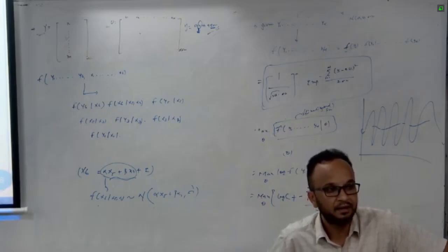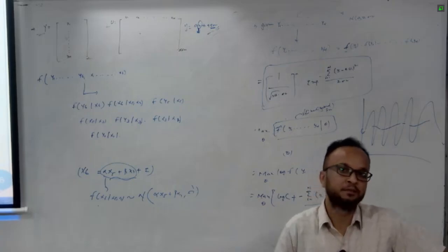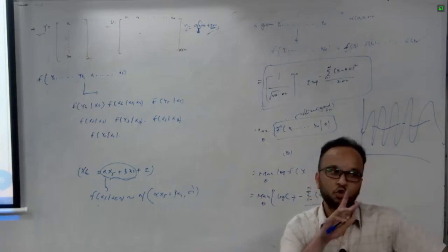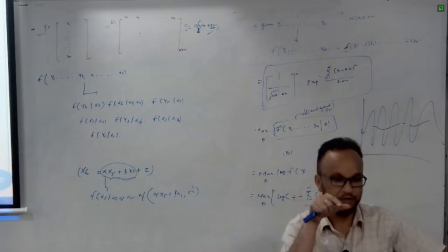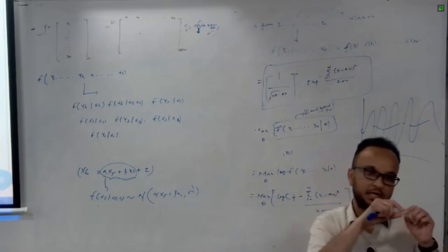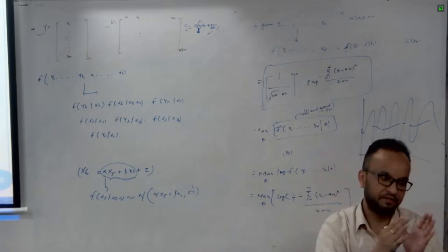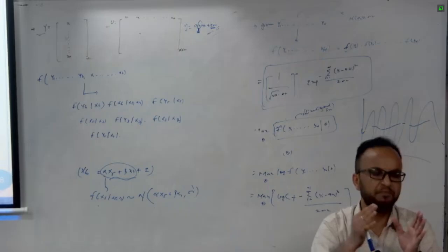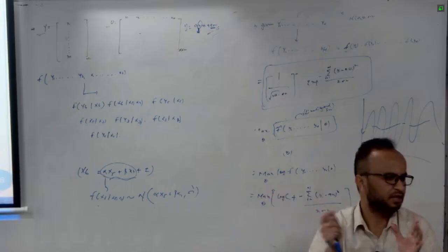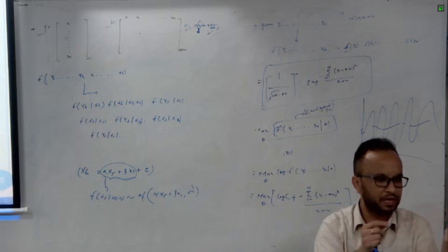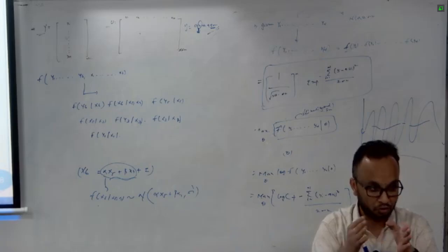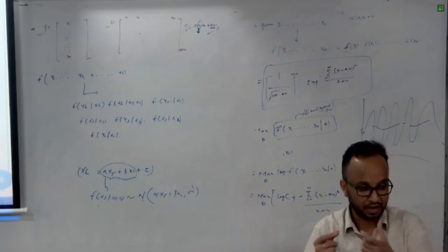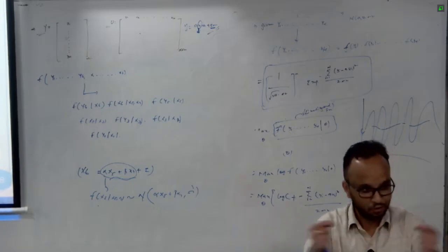There are two ways of filling the data, which we discussed in the morning session. One way is to use the previous value. Suppose the sampling frequency is very high, every 1 minute you have samples and some samples in between are missing, you are getting none. Then you can use the previous value, or an average of previous values, a time series average. But suppose the frequency of data is very low: one sample comes at 1 hour, the next at 6 hours, 7 hours. I can't use the previous value, because you don't know what is happening in between.